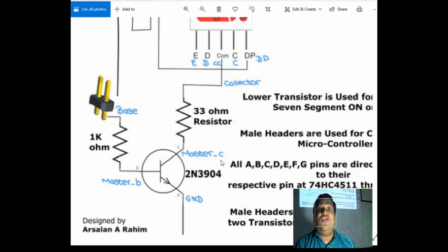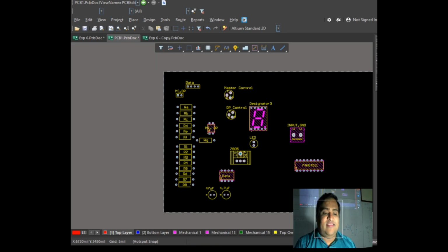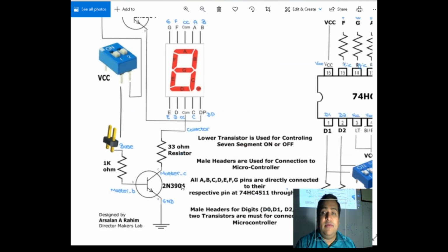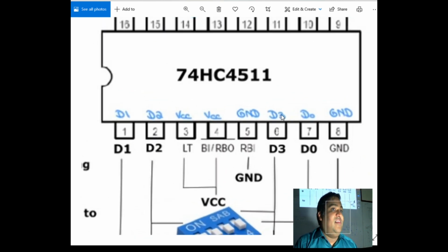These are all the names of the nodes, which are technically called a netlist in our software. Now what do I mean by netlist? Netlist are the nodes which are inside this diagram, and you have named them according to your understanding. I strictly advise you not to name any of the nets 1, 2, 3, 4, 5, 6, 7, 8, 9. Why? Because for small circuitry this may work fine, but when you go for debugging of any PCB, it will be very difficult. So always make the names of your netlist according to your easiness and your understanding.